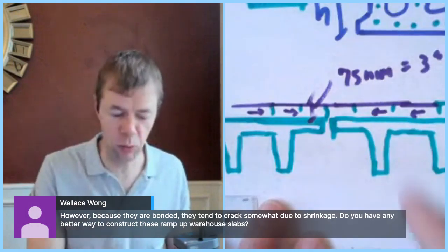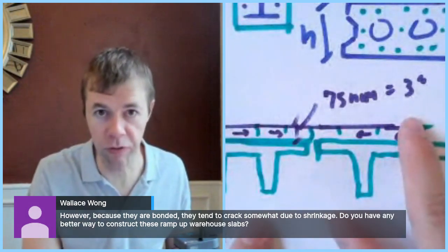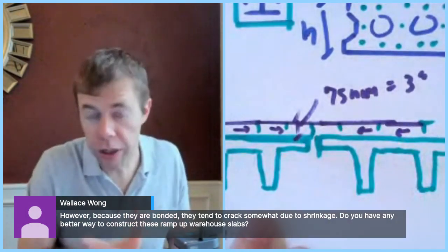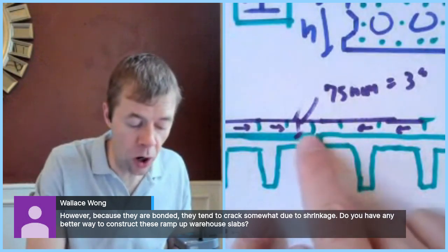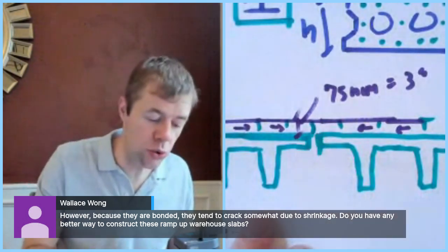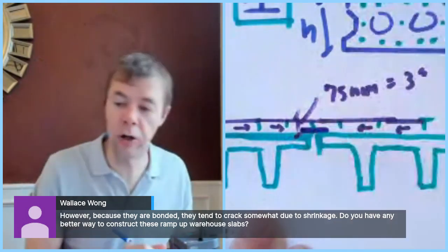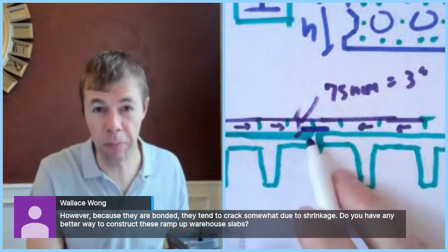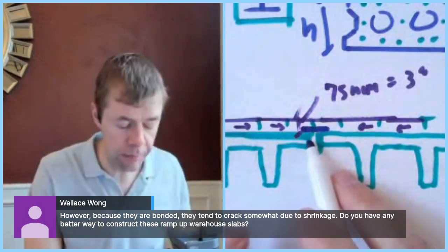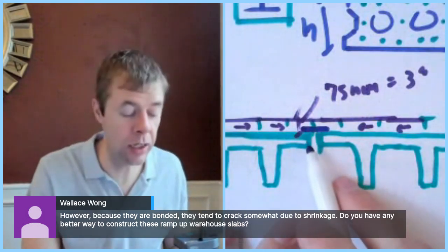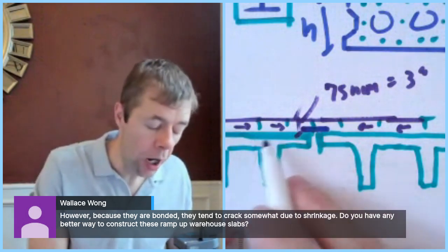You might say, whoa, 3 inches, I don't put any reinforcing bar in there. Well, you could put it on the deck. You could actually drop it and leave it right here. Put bar right here. Put mesh right here. Put it right on top, and hold it down some way. I've seen that done, and that can work well.